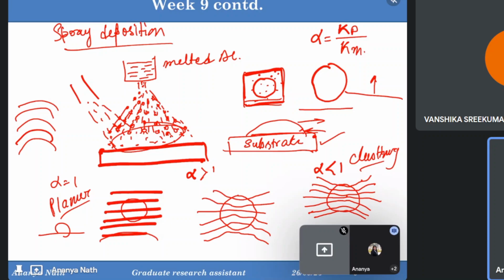This type of atmosphere you can form. You can play with the stacking fault energy with the heat treatment, with severe plastic deformation, then heat treatment may resolve your issue of strengthening. Obviously, the strength of the non-heat treatable alloy can never be equal to the strength of the heat treatable alloy, but it can go somewhat around the heat treatable alloy strength.